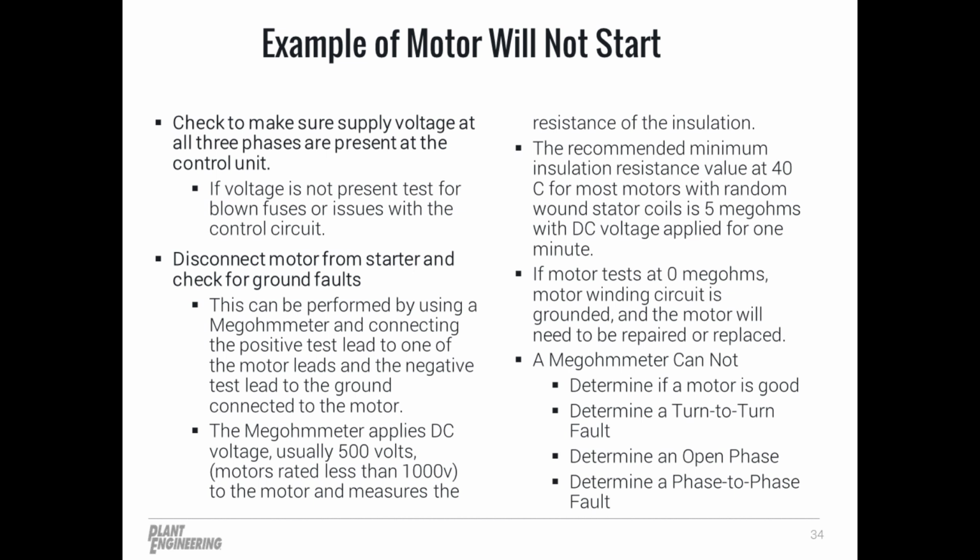Low readings may indicate reduced insulation conditions caused by contamination or deterioration from excessive heat. But if the motor tests at 0 megohms, the motor winding circuit is grounded and the motor will need to be repaired or replaced.